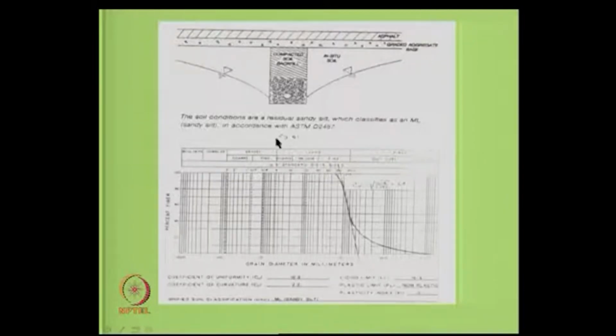That is the type of case, actually, that I want to describe. Suppose you want to have a drain system like this, and the objective is to see that water should not be at the top of this, because otherwise it is very difficult to park the vehicles. So, you would like to lower that, and then you came out with a design that it should be about, say, 1.2 meters below the finished grade. Then what we do is that you also have a gravel here, and you also have a pipe here, and geotextile is placed here.